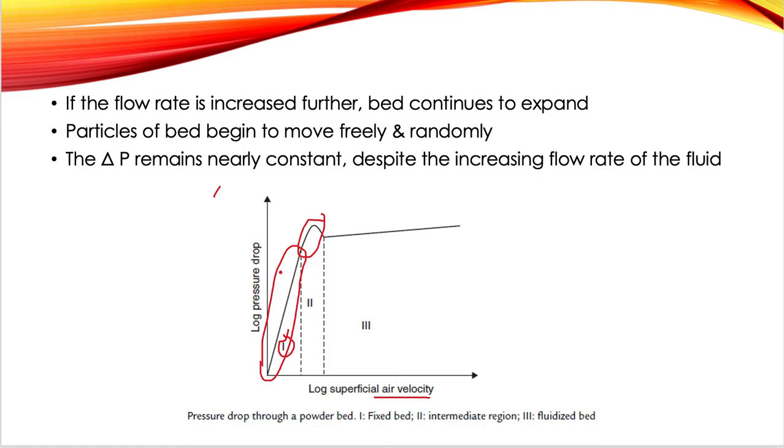And once they reach here, this drop, this phase is what we call continuous fluidization. Within this range of velocity where the bed is fluidized, once the particles have been fluidized, the velocity of fluid in contact with the particle is higher than the velocity of the fluid that has passed through the bed. This phenomenon causes particles to go up and back to the bed instead of being dragged by the fluid.